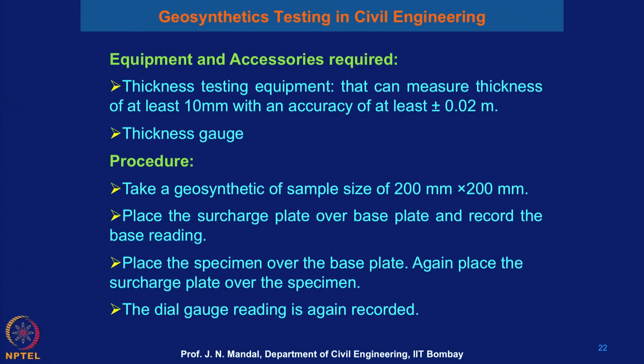So, you need the equipment and accessories required. Thickness testing equipment that can measure a thickness of at least 10 millimeter with an accuracy of at least plus minus 0.02 millimeter. You need a thickness dial gauge.